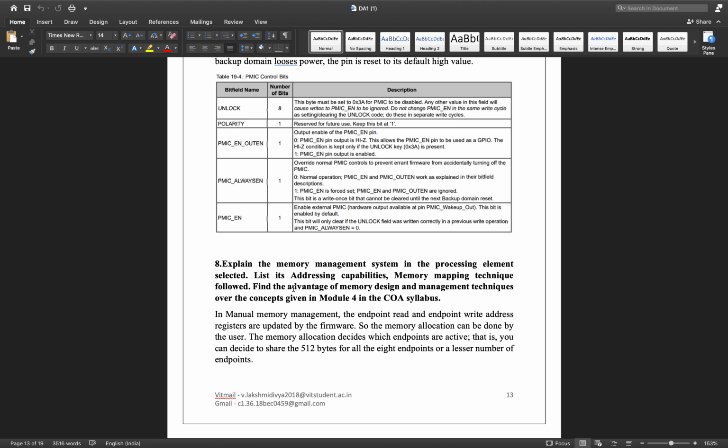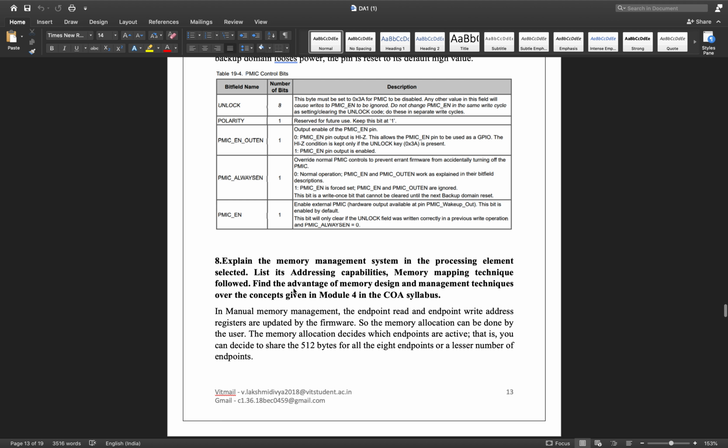Cortex M4 and Cortex M0 Plus have ARM memory protection units, also known as MPUs, for protection at the bus master level. Shared memory protection units help in protecting memory resources that are shared among the multiple bus masters.